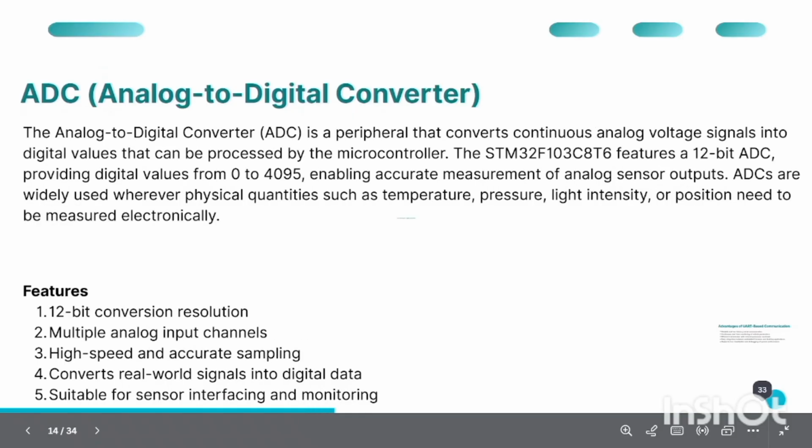ADC mechanics. To read physical continuous voltage, we configure the STM32's on-chip 12-bit ADC. The 12-bit resolution translates analog pedal position into precise digital integer values from 0 to 4095, giving our powertrain control algorithm highly accurate driver intent data.